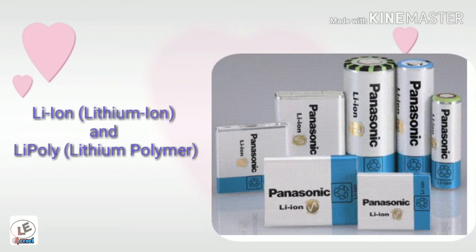Lithium ion or lithium polymer is the latest rechargeable battery technology, and it is quickly becoming very popular. They are the most common batteries for consumer electronics like camcorders, cell phones, laptops, etc. They are very lightweight and lithium ion cells are basically 3.6 volts. So 3.6 volts and 7.2 volts are the most common battery voltages you can see in this type of battery.